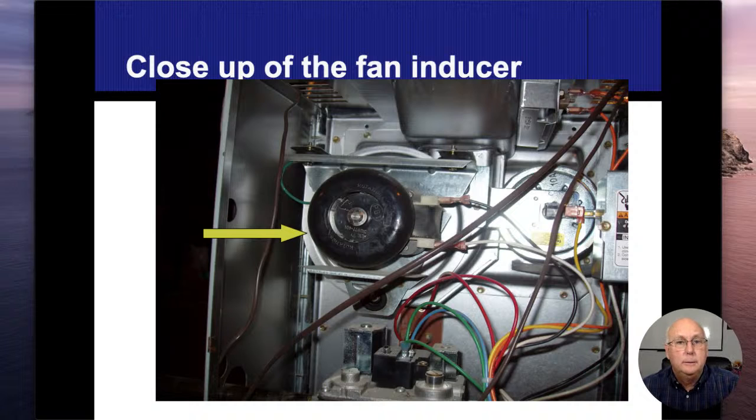Then the computer basically checks all of its quick circuits, makes sure it's okay. And the first thing the computer activates that we're going to see operating is going to be this inducer fan. So that wheel is going to start spinning.